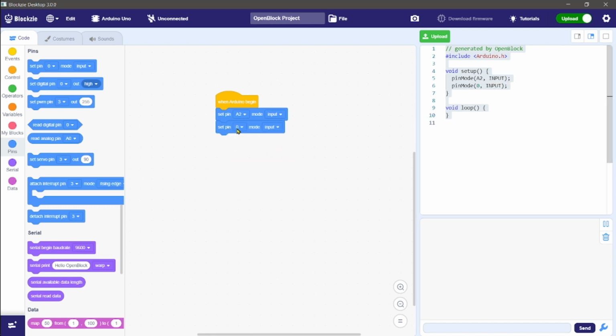After that, we have connected the LED on pin number 11, because pin number 11 is also a PWM pin. As we have discussed earlier, on the Arduino Uno board there are 6 PWM pins. PWM means pulse width modulation, which means you can control and vary the output. Hence we are using pin number 11, and that LED is our output device, because we are getting output in the form of light emission. Hence pin number 11, which is a PWM pin, is set as output.